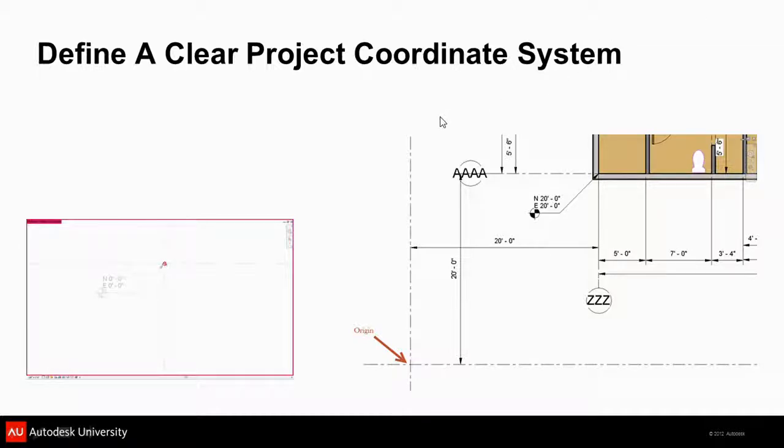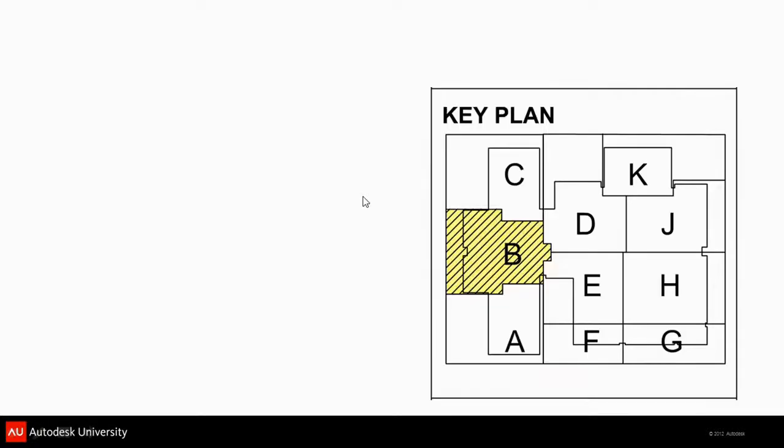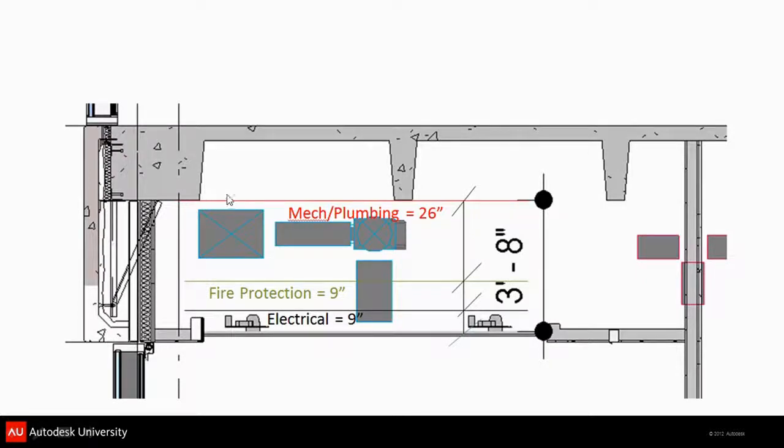Another thing I think is really important is that everyone on the team, when you're trying to run the plumbing, has defined coordinate systems for the project and everyone's using the same. When I'm trying to coordinate plumbing, we only look at one area, a plan at a time per meeting. We talked about this a little before. This is what we call a wedding cake. This is where we take a section through Revit early on and then just have a discussion with people on the team.